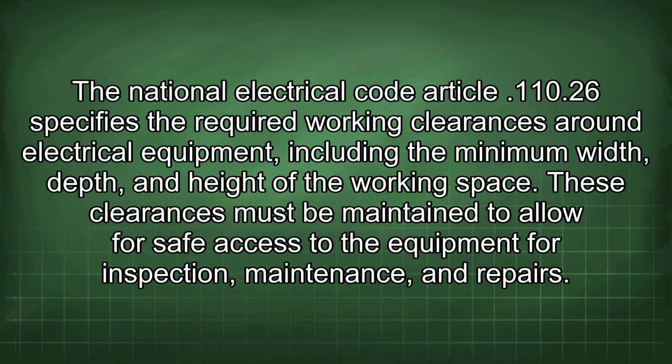The National Electrical Code Article 110.26 specifies the required working clearances around electrical equipment, including the minimum width, depth, and height of the working space. These clearances must be maintained to allow for safe access to the equipment for inspection, maintenance, and repairs.